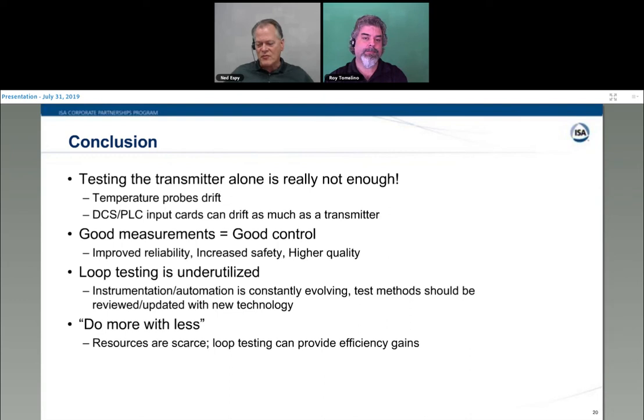Well, they drift and then they fail, depending on the conditions of your process. But yes, you can't calibrate a probe. To fix it, you have to throw it away and put in a new one. But you should check the new one too and make sure there's nothing else going on that's causing a problem. You'd catch it when you install the new one. That's true. I just want to put to rest the misconception that a temperature probe is flawless or it doesn't work. That's simply not reality.